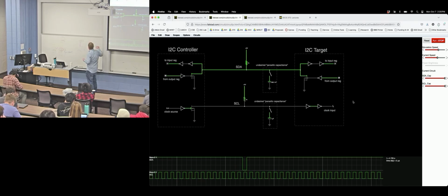There was a project where I put too high a voltage in here, and I actually started changing the VDD of the chip, which was still within spec, but the ring oscillator that I was using started changing its frequency because now the whole chip was at a different voltage. And so certain times when my little RFID tag was working, it would work fine, and then when I brought it close to the device, it would overcharge this pin, and then the clocking would get bad. So I had to learn a lot. All right, anyways.